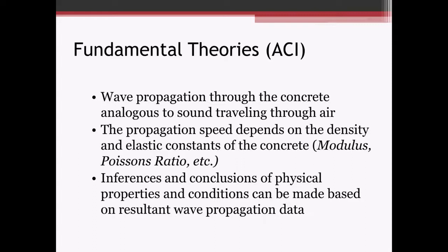Again, they might be quantitative conclusions, like pulse velocity. We can get the velocity of the wave traveling through the concrete. Sometimes they're just qualitative, where we're comparing one area to another area, maybe trying to delineate areas of poor consolidation or weaker concrete or something like that.